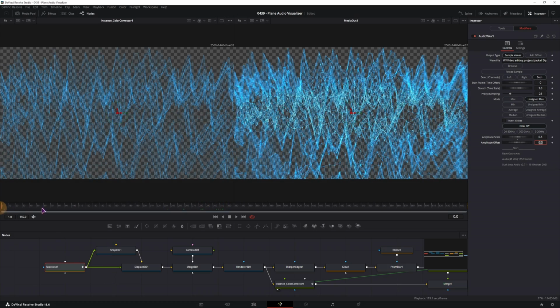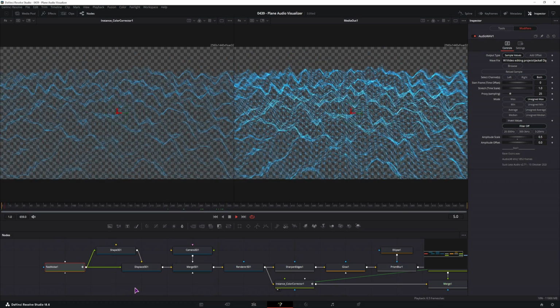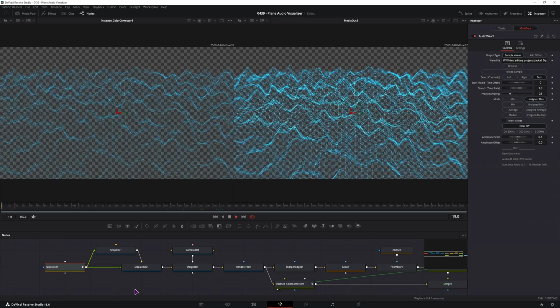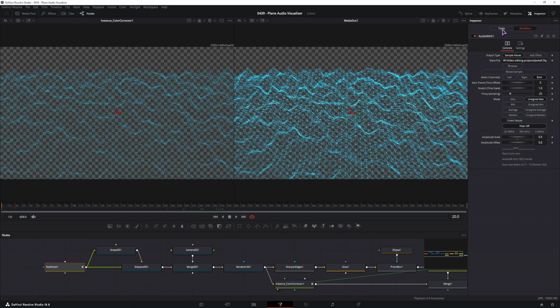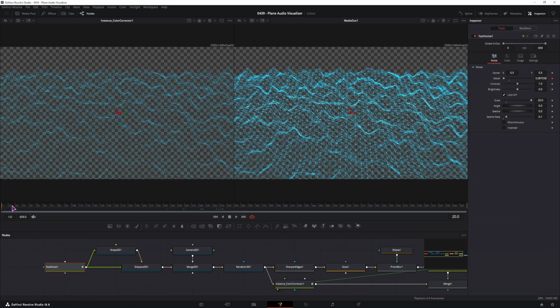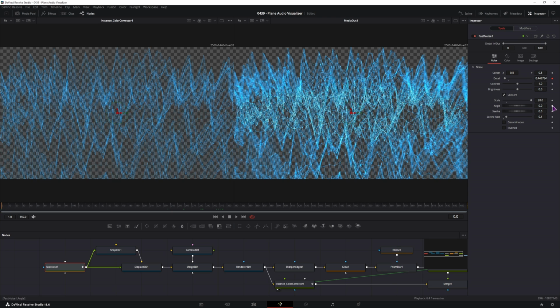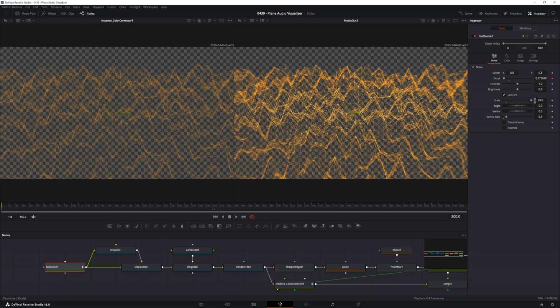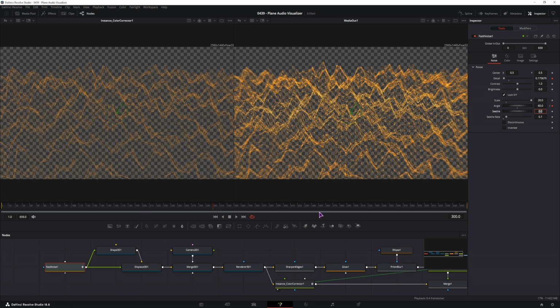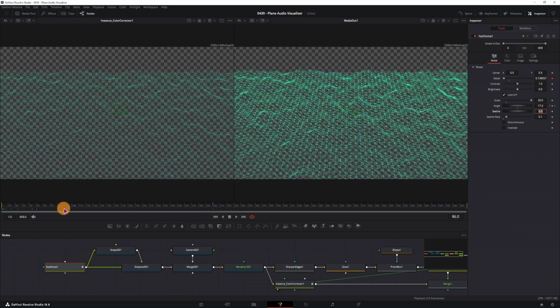And the last thing that we can do to spice it up just a little bit more is in the fast noise node. We can go to the angle. I'll go to the beginning. I'll keyframe the value. Maybe in 10 seconds this will do 60 degrees. Type in 60 and press enter. So now this will rotate slowly, as you can see.